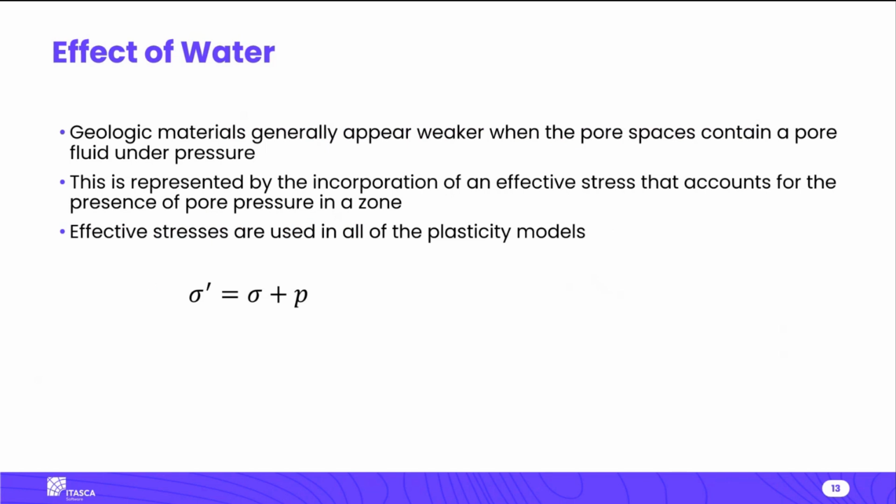Just one quick mention about the effect of water. There's a whole other session about water in 3DEC, but it is important to mention here while we're talking about constitutive models that when 3DEC is checking to see if a material has failed, so it's checking the stress state versus the strength, it uses the effective stress state. So if there's pore pressure in the model, it will use the effective stress state. It essentially reduces the stress, and it uses that to check if the material fails or not. So pore pressure will have an effect on the potential failure of models in 3DEC.